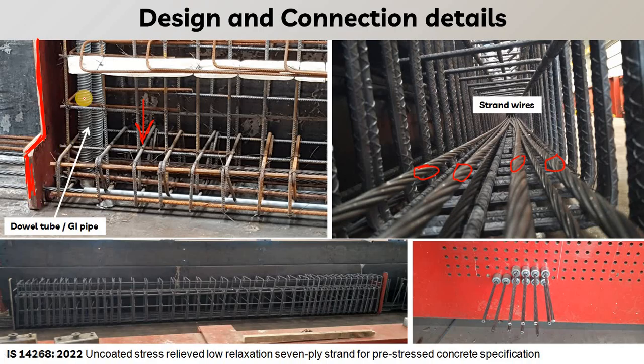And here you can see the silver corrugated pipe. That is known as the double tube, which will be passed throughout from the bottom to the top, in which the reinforcement that will be projected out from the column will go through this tube, and this tube will be filled with the special grouting material, which is known as grout, to connect this element. So this kind of tubes on both sides of the beam will be considered.